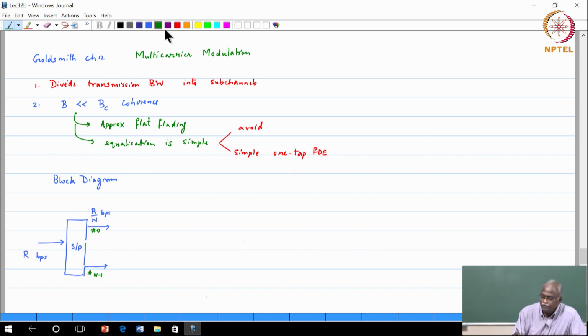Okay. Now, each of these channels, let us quickly trace what the path of them is going to be. You will group the bits into either 2 bits or 3 bits sets, and then map them onto a symbol. So, the first stage will be a symbol mapper. You will map it to either QPSK, 16 QAM, 64 QAM, whatever you want. Then the next stage is you have to prepare it for transmission. You will do pulse shaping. Pulse shaping is to ensure that you have a compact bandwidth. So, raised cosine, any of those types of pulse shaping is permitted, that is done.